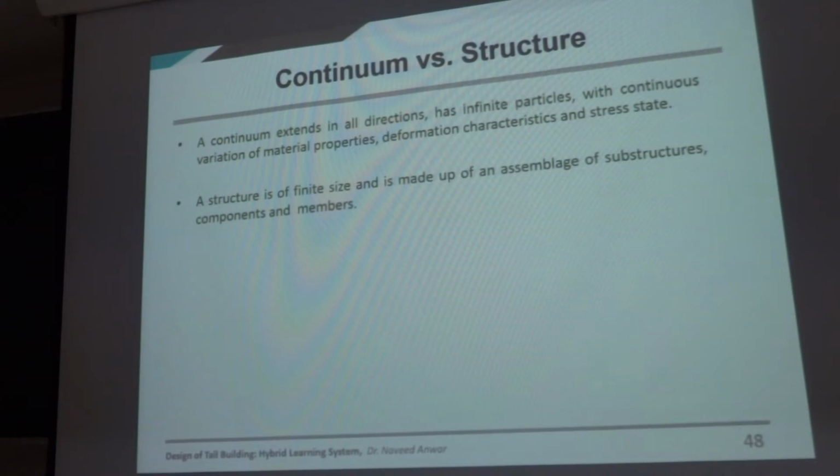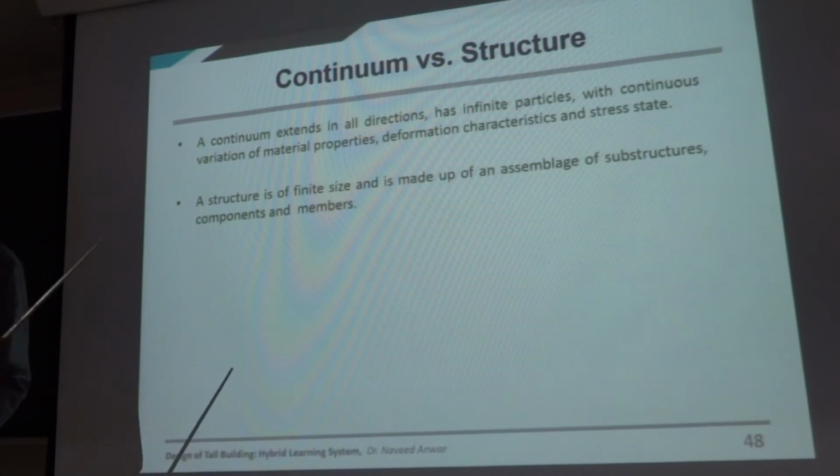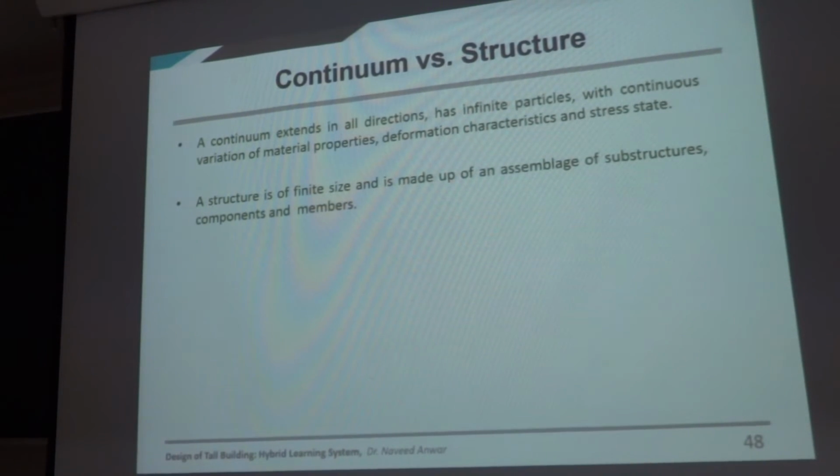And then the question is, how far are you going to go? Keep modeling the soil, right? Actually, you can go very far. In London, if you construct a new building, you actually have to model one block of the city, the soil and all the buildings on it, to prove that your building is not going to have any detrimental effect on other buildings.